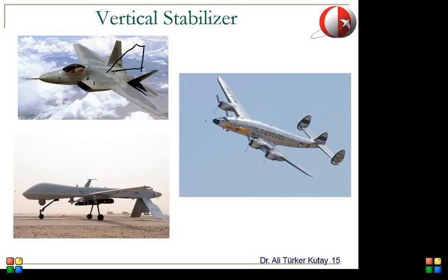And there's another disadvantage to having a large stabilizer. This is a fighter airplane, and large surfaces mean that the aircraft will be easier to detect using radar waves.